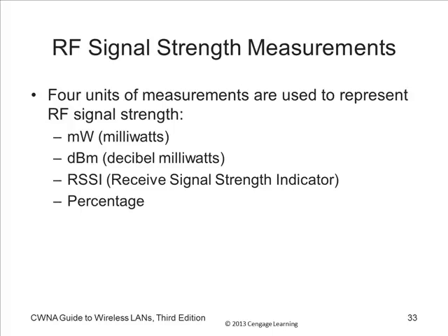dBm means that we start with 1 milliwatt and we go up or down. So we have milliwatts, dBm, decibels, milliwatts. We haven't really talked about what a decibel is. A decibel is a relative measure.